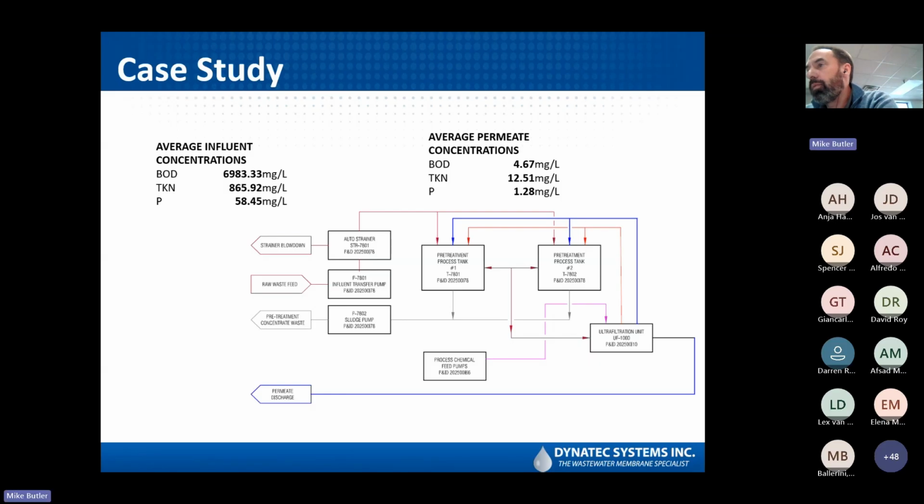The way this would work is process tank number 1 would be used to feed the ultrafilter for a day. At the end of the day, or early the next day, the feed from the plant, or the plant effluent to the wastewater plant, would switch from tank number 1 to tank number 2. Tank number 1 would continue to be concentrated down using the ultrafiltration skid until it reached its maximum concentration, and then it would be pumped to a concentrate holding tank that would then be emptied by the renderer.